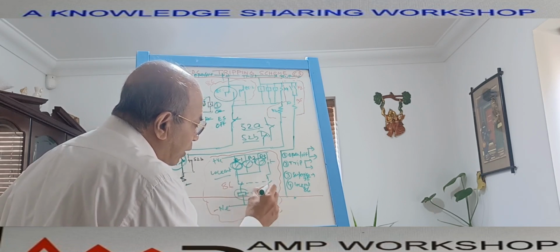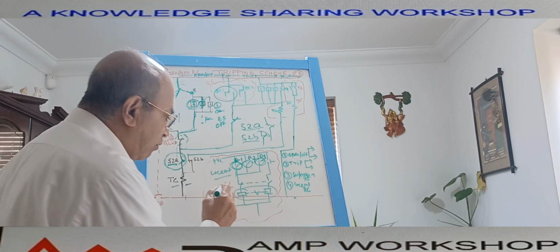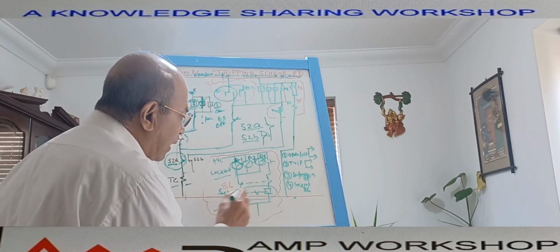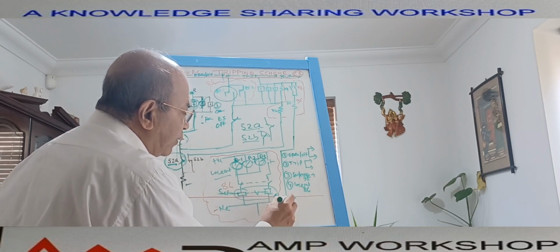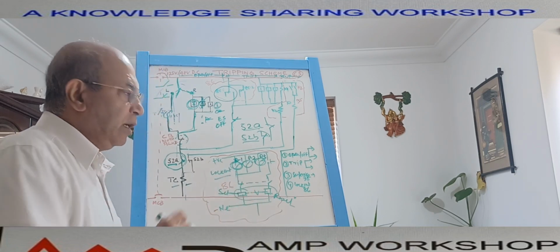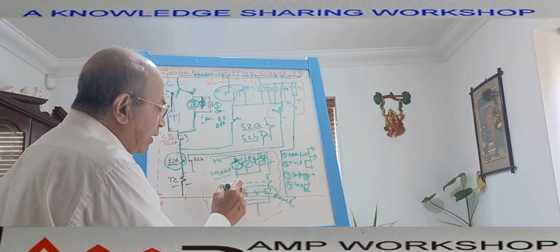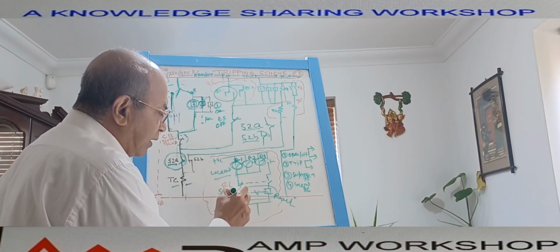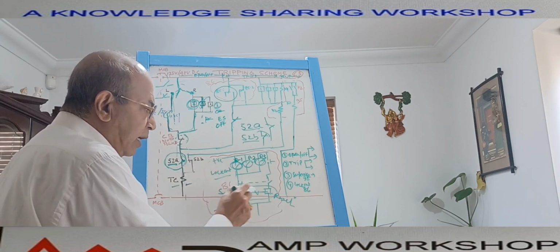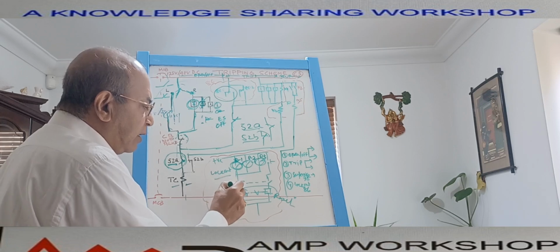This is the lockout relay. We call these the two coils. One is a set coil and the other is a reset coil. The set coil is energized by the protection function of this digital relay. The lockout relay has one NC contact connected through this. When the relay is not energized, it is in the NC condition.